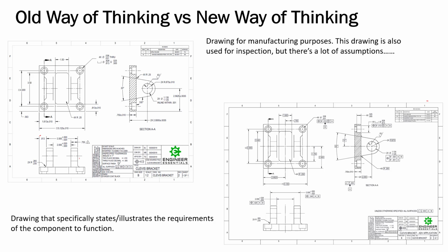So we will work with our customers, our students. We will teach what I always call cheat methods. They're not really cheat methods. We're still trying to adhere to the standard. We're still trying to adhere to the correct inspection of this complex profile, but we're trying to find an easy way to do it, something that doesn't require the CMM. So we help customers with that. And again, we're not breaking the rules of the standard. We're just trying to find a workaround that's realistic and doesn't force somebody to either remove profile from their print or to go out and buy a $50,000, $100,000 CMM in order to inspect a single part.